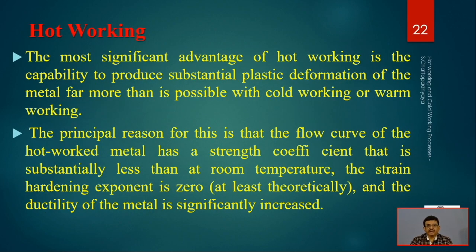So the most significant advantage of hot working is the capability to produce substantial plastic deformation of the metal, far more than is possible with cold and warm working, because cold and warm working take a lot of effort. Some stubborn materials are not ready to deform easily at lower temperature. A lot of force is required. So it is better to elevate the temperature so that they are negotiable in terms of deforming.